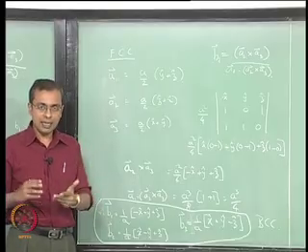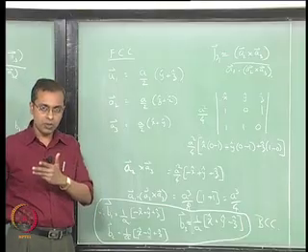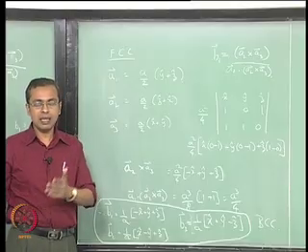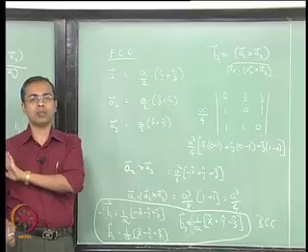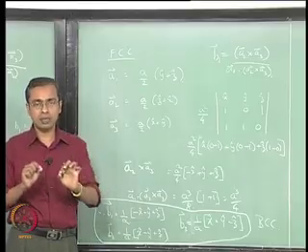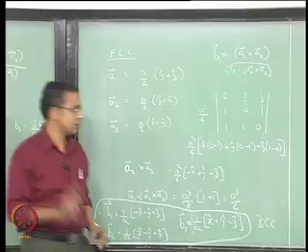When we want to understand how it is interacting with radiation, and we want to use the reciprocal lattice notation to see how it is interacting with radiation, we see how this structure is represented in reciprocal space. It is simply a representation of the face centered cubic structure in reciprocal space, that is all. The material still remains FCC, that is the thing you have to remember.